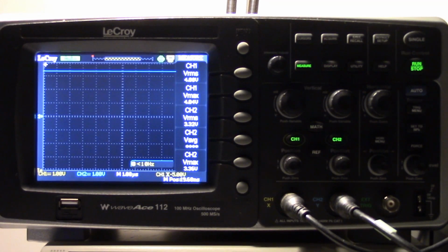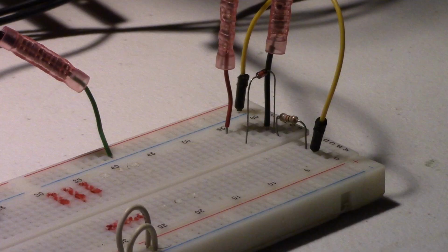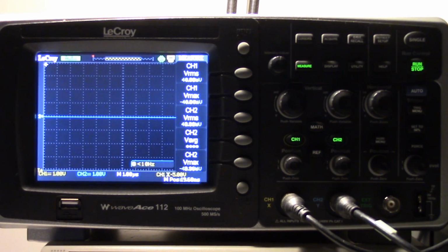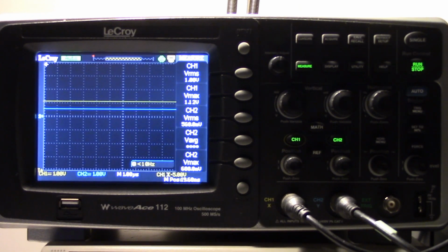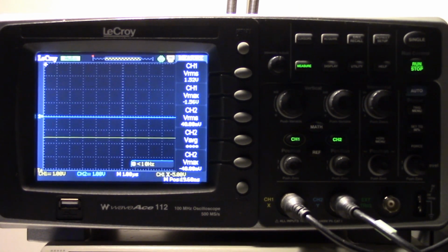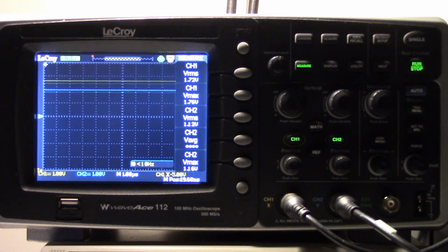Okay, and so what I have here now is my oscilloscope and the circuit here. So what you want to do is have a signal generator, and set it up so that it goes through sweep mode. And when it goes through sweep mode, you're going to be sweeping through your entire voltage range, as I'm doing here right now.